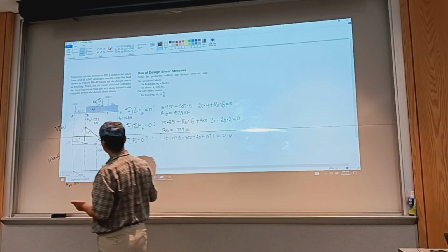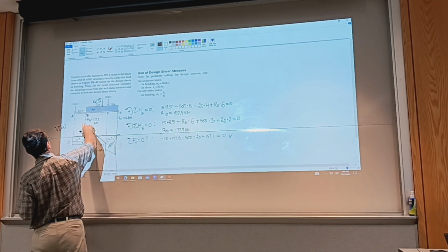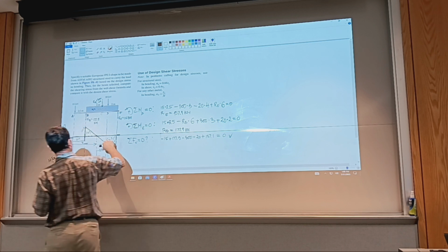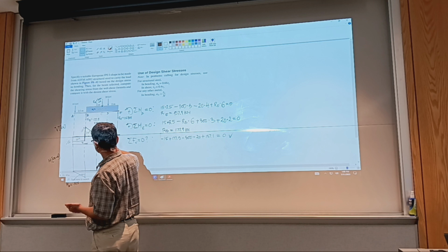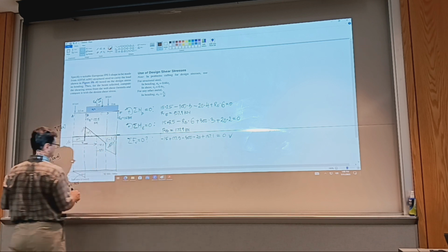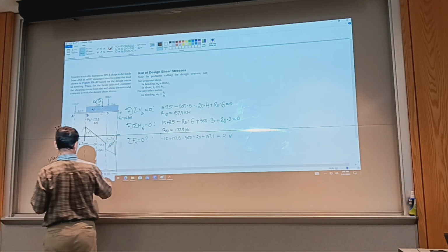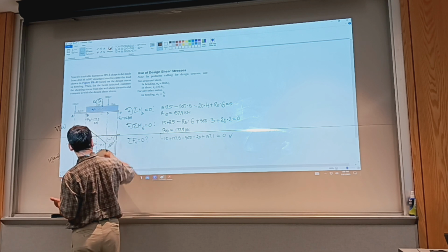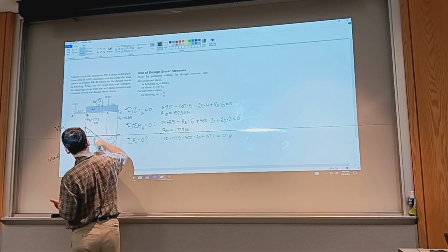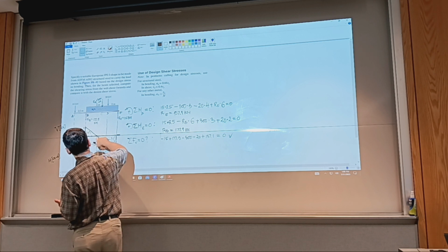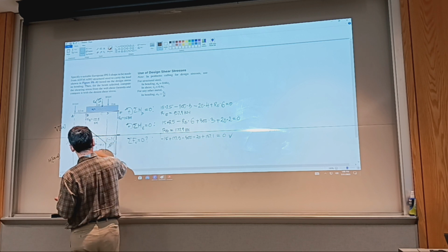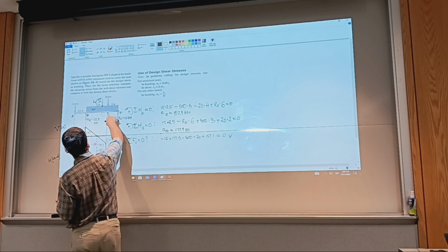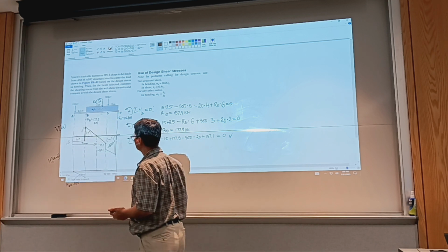And it starts with a positive slope, goes to 0 and ends with a negative slope that is less. Well, I can evaluate what the moment at D is. I need to also know where to reverse the parabola, where it reaches its maximum. So let's see what the moment at point D is.